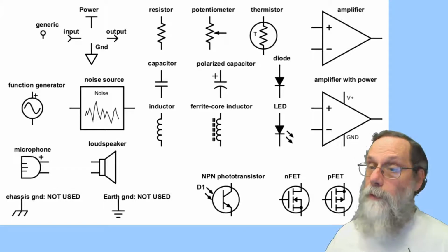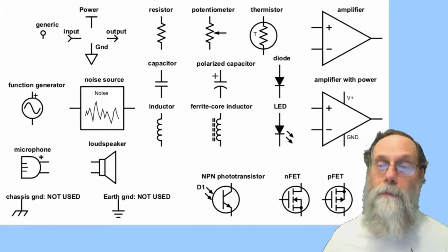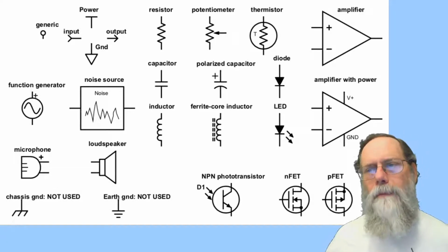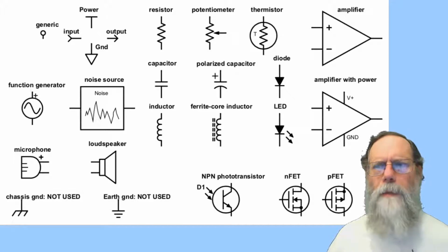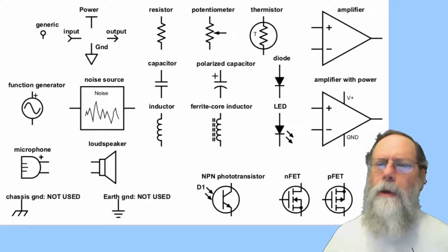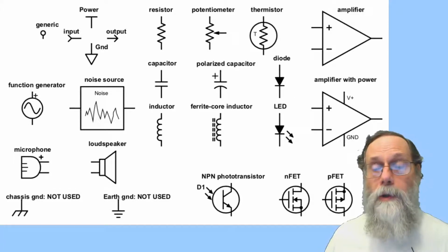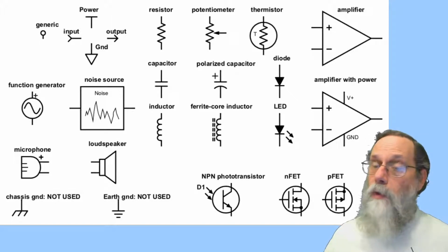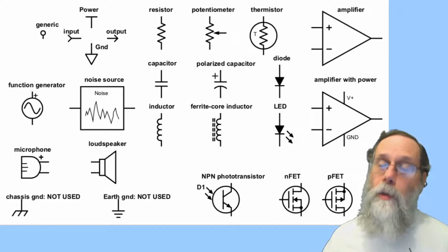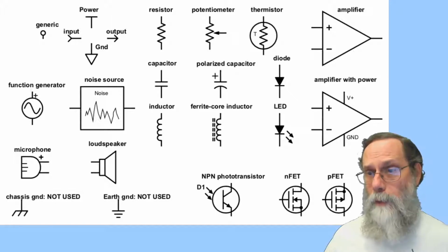They're also used for that same sort of connection which goes between pages of the schematic. But they're not used a lot for that purpose unless you have a bidirectional connection, because it's much more useful to your reader. And remember, schematics are intended for human reading. It's much more useful to your reader to indicate which direction information is flowing. So we usually use input and output ports.